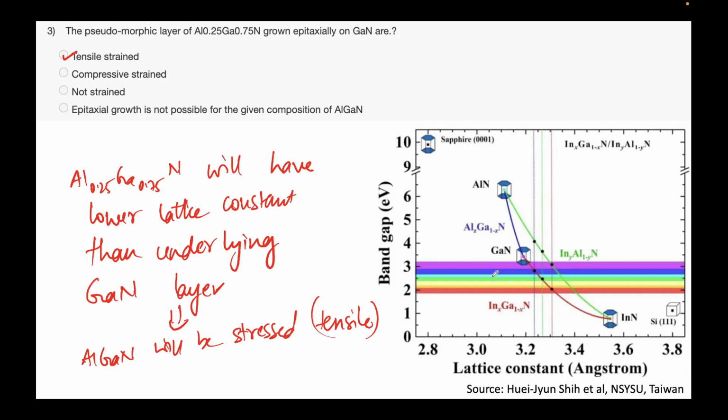They exhibit enhanced or reduced electrical properties. So that plays a very important role in the device which you had seen in question 2, the HEMTs, the high electron mobility transistors. This effect is particularly used: the stress of the upper layer, and in this case the gallium nitride layer, how much stress you want it to be is of primary importance. So that is about this problem.